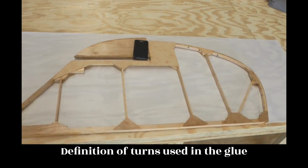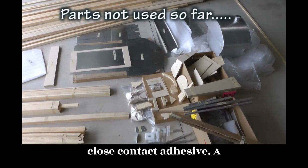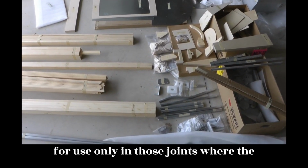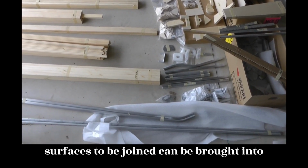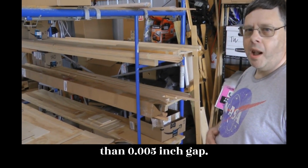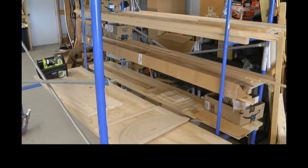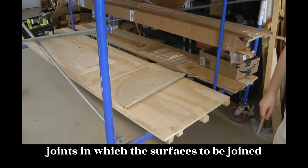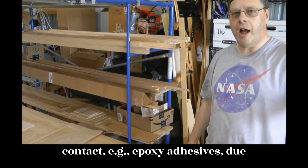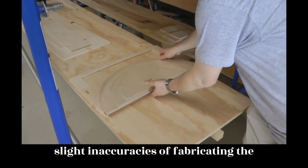Definition of terms used in the glue process. 1. Close contact adhesive. A non-gap filling adhesive, e.g., resorcinol formaldehyde glue, suitable for use only in those joints where the surfaces to be joined can be brought into close contact by means of adequate pressure, to allow a glue line of no more than 0.005 inch gap. 2. Gap filling adhesive. An adhesive suitable for use in those joints in which the surfaces to be joined may not be close or in continuous contact, e.g., epoxy adhesives, due either to the impracticability of applying adequate pressure or to the slight inaccuracies of fabricating the joint.